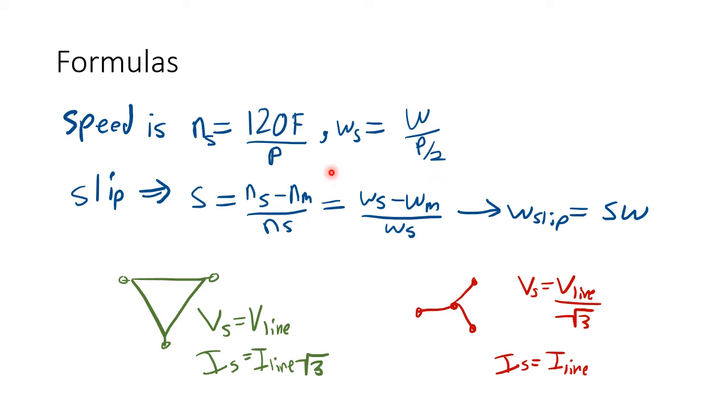And then with these two formulas, you can derive a bunch of other formulas, but honestly, once you get your S, you find omega slip, which can be used to derive other calculations. You can go a lot more into this to determine what happens if, like in the previous slide, the resistance of the core changes, the resistance of the stator changes, and in each case there's a specific phenomenon that's going to be seen. But this is just a brief video.